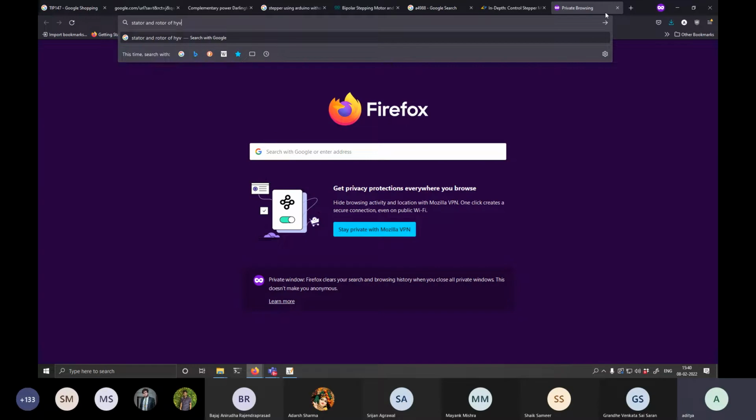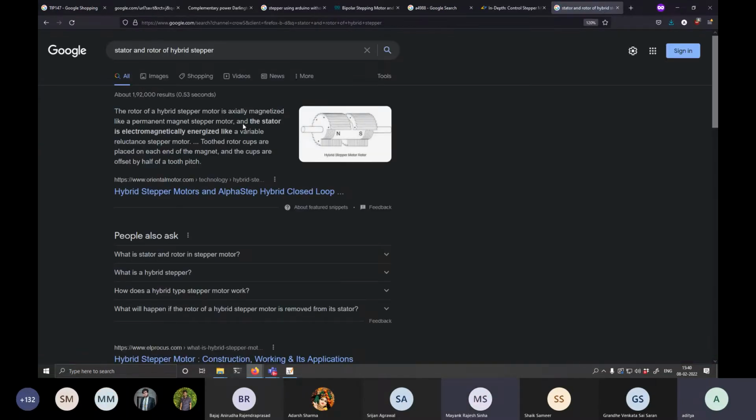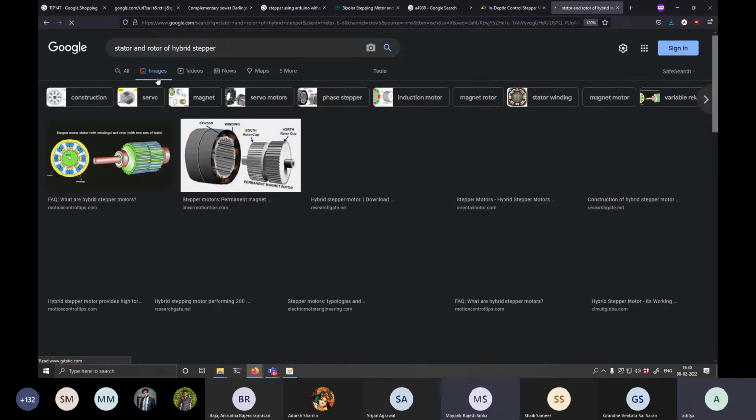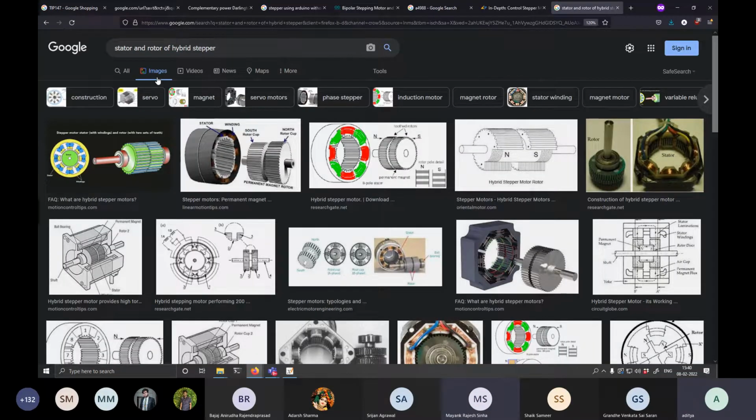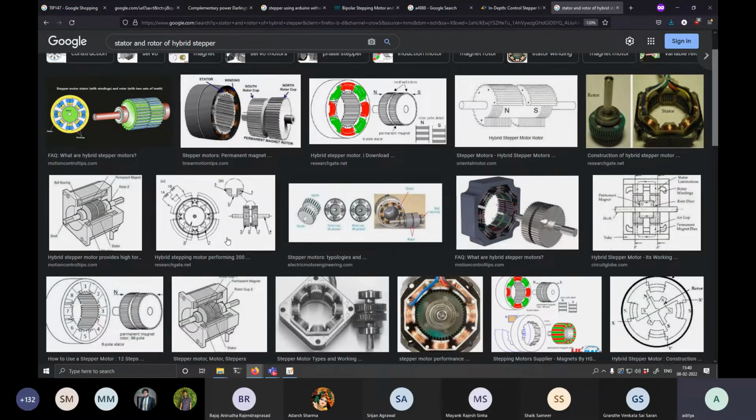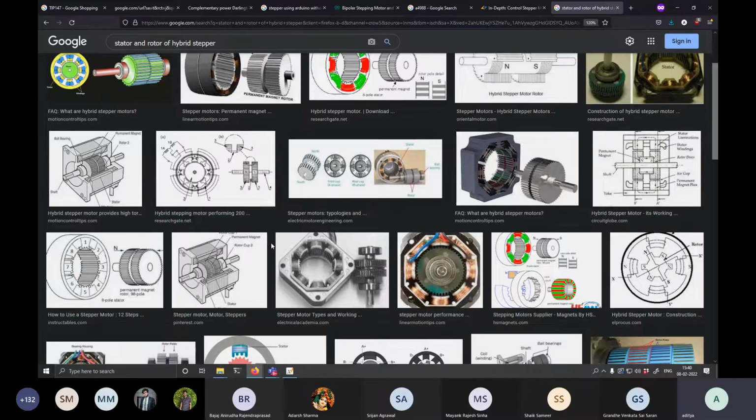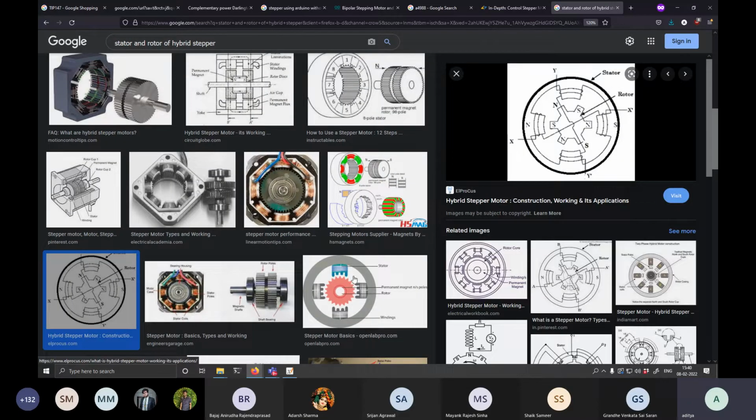So the timings for which each coil gets excited, is it calibrated so that it matches the time it would take the magnet to rotate? It happens very quickly, but if you try to get too high of a speed, then it will not work. You will start what is known as missing steps. You will eventually start missing steps.